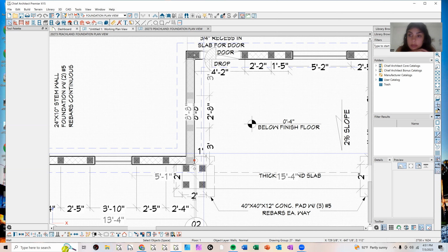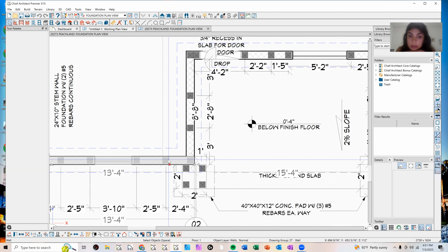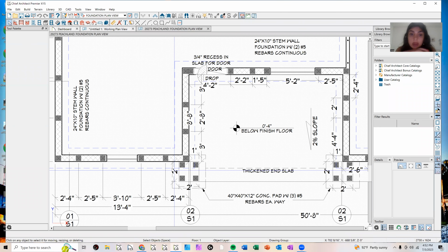When you pour the slab, they have those rebars already in. You've seen it, right? And then they stack the CMU blocks over them. And this is every single place where we're putting a piece of rebar and where we're going to be filling the cell full of concrete. So you understand that. You've been taught that already?